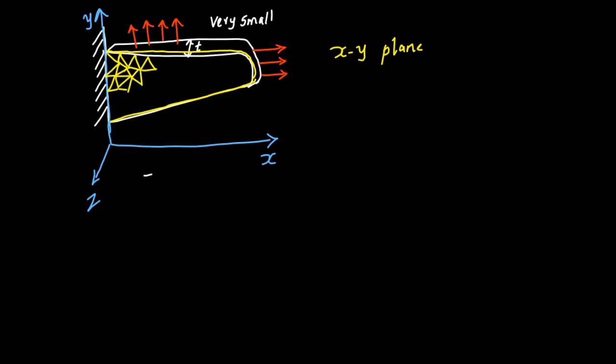Okay. What you are actually going to do is you take out one triangle. I think the triangle looks like this. And you are actually going to derive the shape functions for this particular triangle. Why do we want to derive the shape functions? Because only then you can find the stiffness matrix. Okay, only then you can find the strain displacement matrix. Only then you can find the stiffness matrix. Of course, you will also need to know the stress-strain relationship matrix.